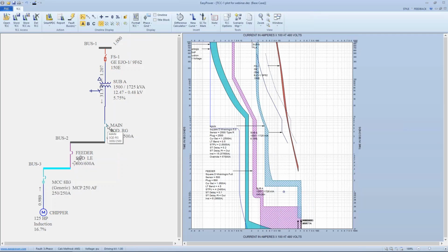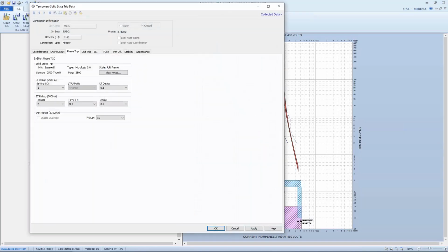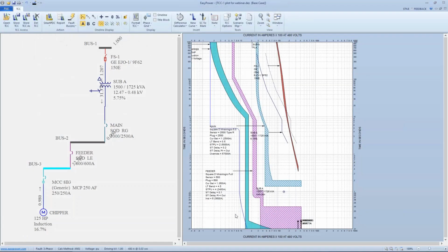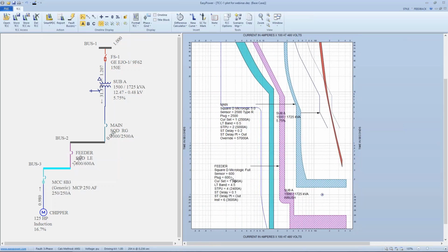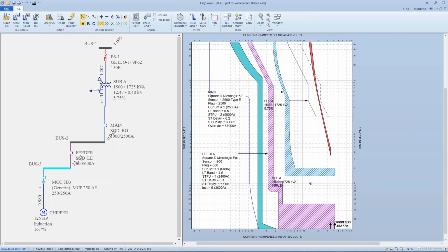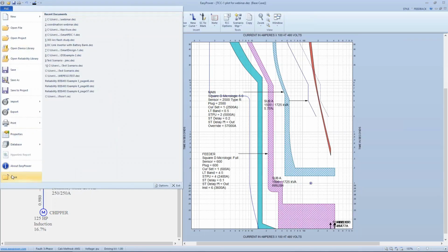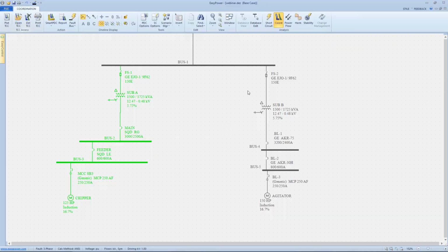Now, because of these particular trip units, we can turn off this trip setting on instantaneous. We just turn it off. And at that point, we have a better chance for coordination at the higher currents. Again, that's because there is a Square D Micrologic sensor trip unit, and we have the versatility of being able to disable that instantaneous trip. If we're using just straight off the shelf, non-adjustable molded case circuit breakers, that's much more difficult. Now, let's talk about low voltage power circuit breakers first, and then we'll go into series coordination.